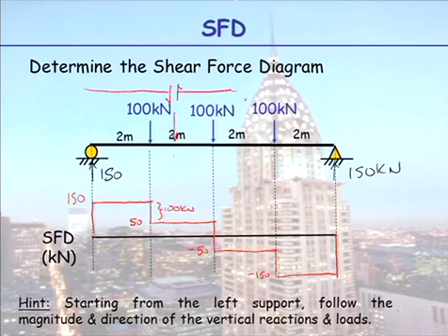If I were to cut the beam in here at this location, my shear force is now minus 50. So instead of my two forces causing anti-clockwise, that would mean my two shear forces are causing clockwise rotation. So that's what the plus and the minus mean. Yeah?